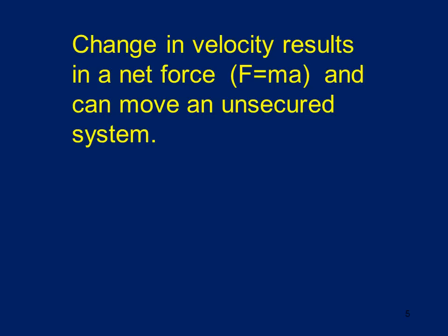Now, the change in velocity will result in a net force because you have an acceleration of the mass. And you recall one of Newton's laws, force is equal to mass times acceleration. And so when you put a nozzle in place, you've got to make sure you have something holding it in place, or it will try and accelerate the whole system. The change in the velocity will try to accelerate the whole system.